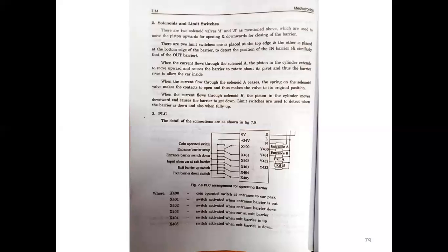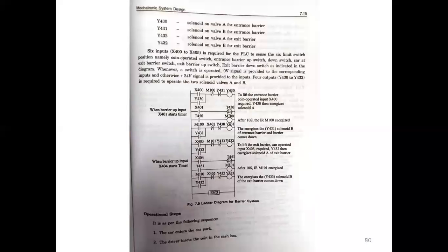Then X400. That is the coin operated switch at the entrance to the car park. So these are the pins connected with the particular application, particular input. Six inputs X400 to X405 are required for the PLC to read the six limit switch positions, namely coin operated switch, entrance barrier up switch, down switch, car at exit barrier switch, exit barrier up switch, exit barrier down switch